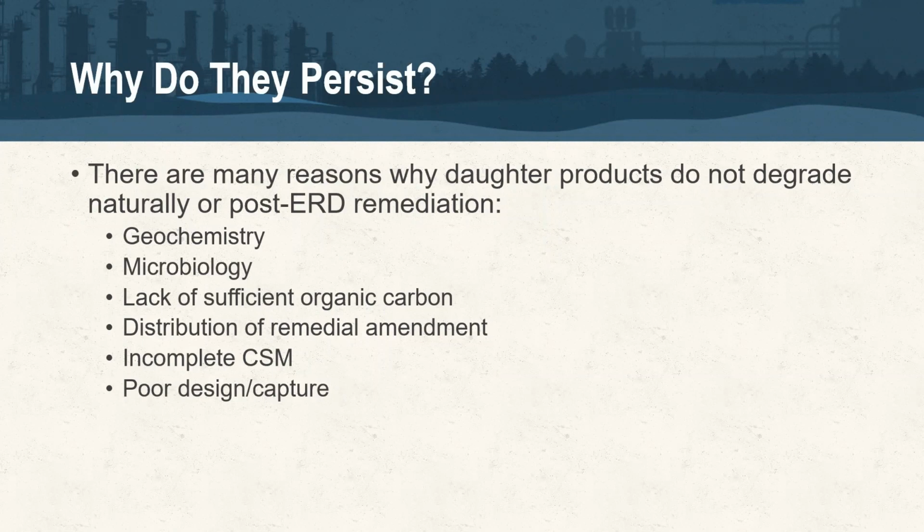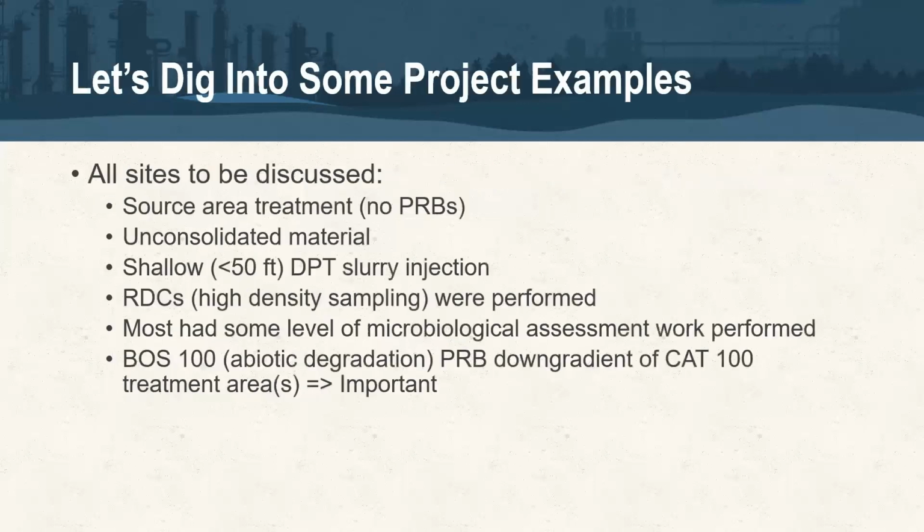And then lastly, for design/capture, what I mean there ties in with my comment before about having a down gradient capture technology that's not ERD based, so something that's abiotic, to be able to capture any daughter products that do ultimately flow out of these source areas.